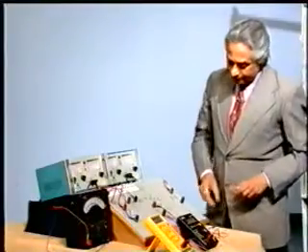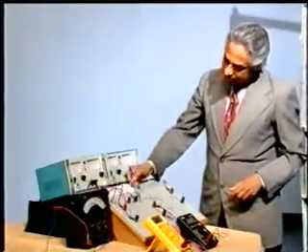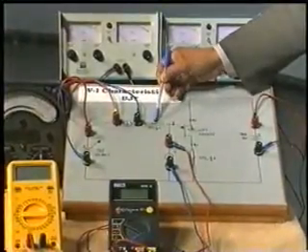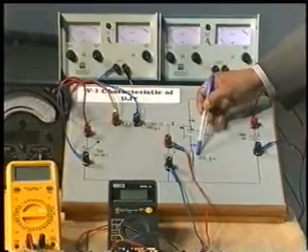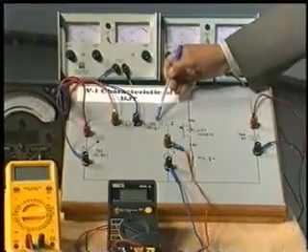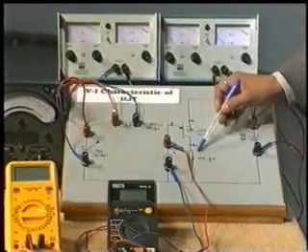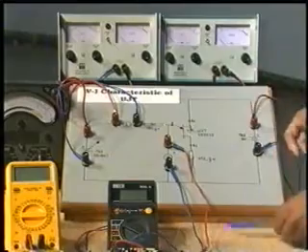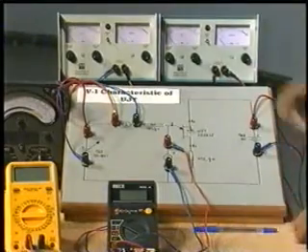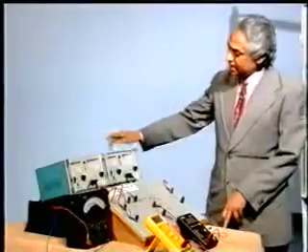Now you see there are two resistors here, one is 1.8 k half watt and the other one is 47 ohms half watt. This resistor is meant for limiting the current and this is connected across B1 for getting the output. Now what these meters are going to read: of course these are the two power supplies.